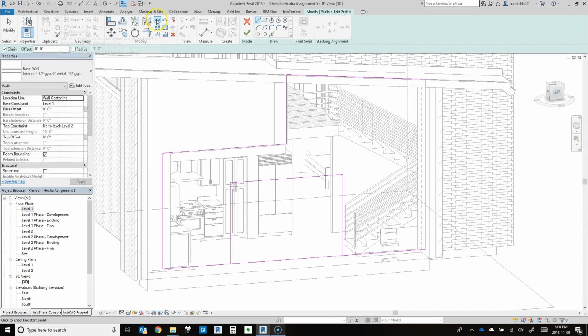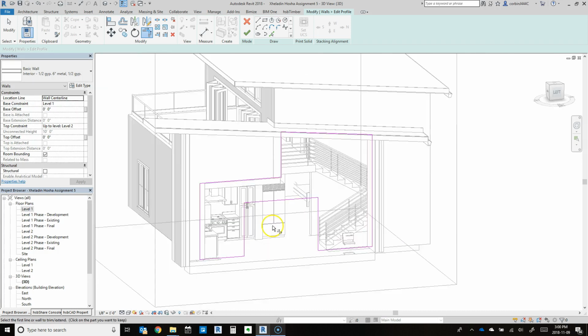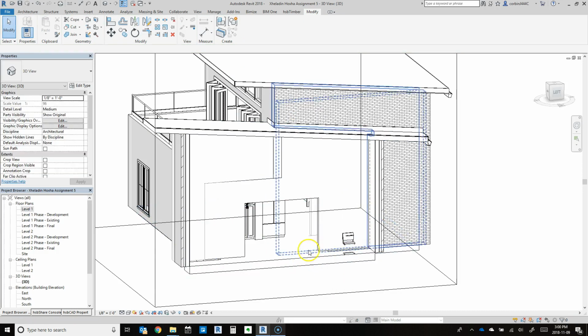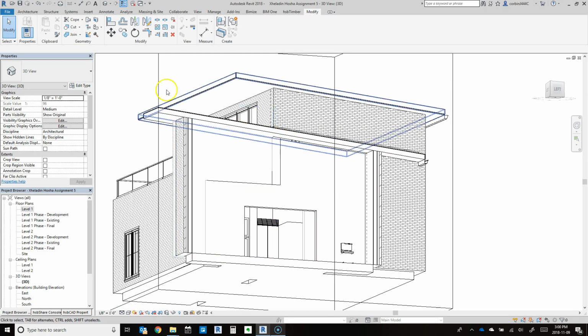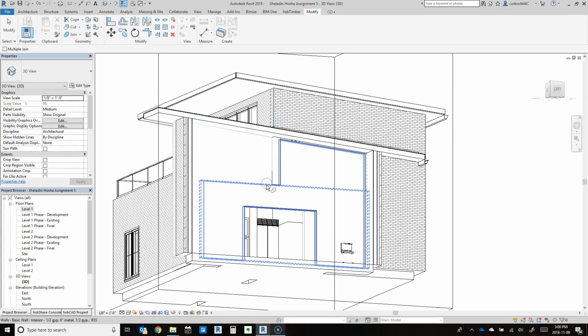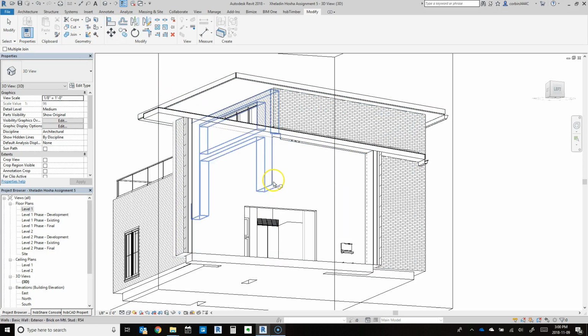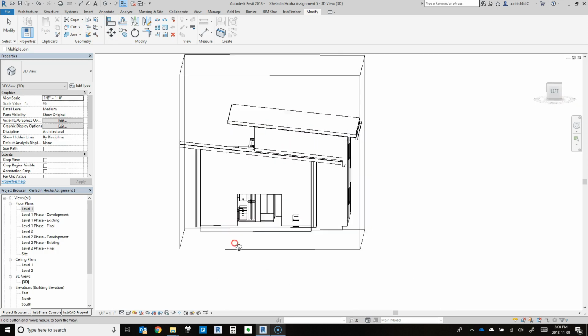We're going to use the break line tool or Split Element tool to break the line. I just clicked the wrong thing there. And we use the Fillet Trim and Extend tool. I say fillet tool because that's the old AutoCAD terminology that has come over. And there we go. To get rid of all these lines, which might not be that important, you just join these elements and some of those lines will disappear.